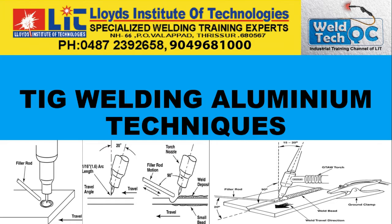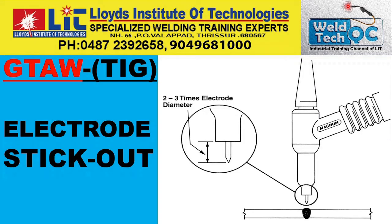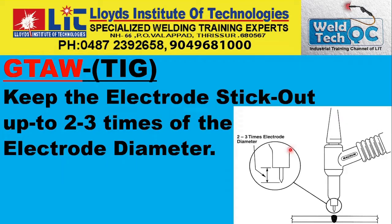Always try to keep a shorter arc, the distance from here, as well as ensure that the electrode stick out is maintained at 2 times or a maximum of 3 times the electrode diameter. That is a point to be noted. Keep the electrode stick out up to 2 to 3 times the electrode diameter, as just said.